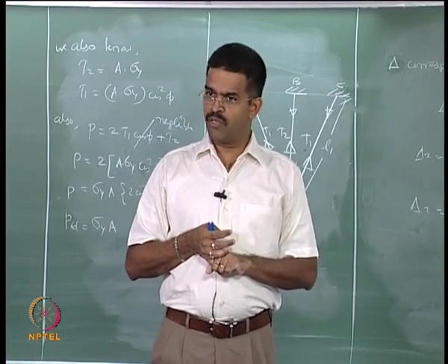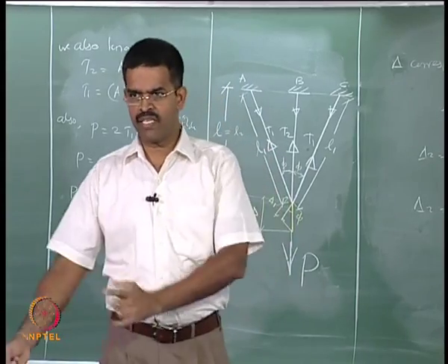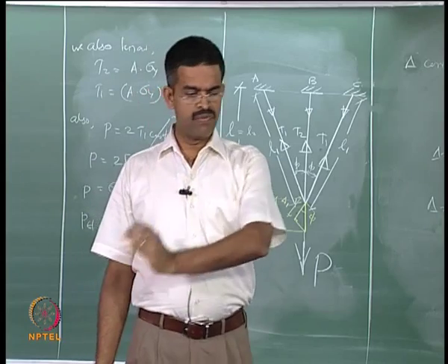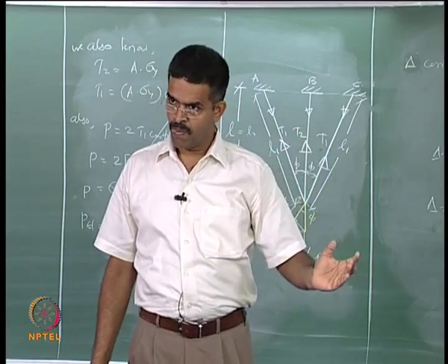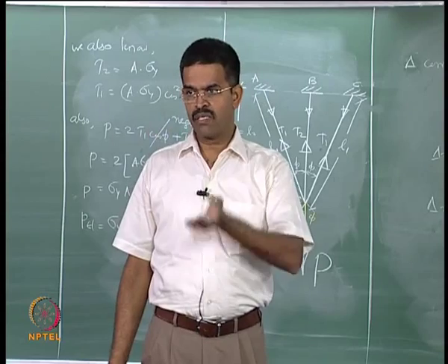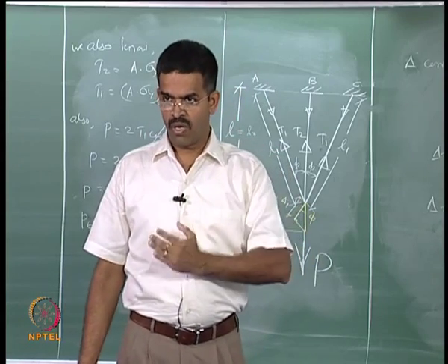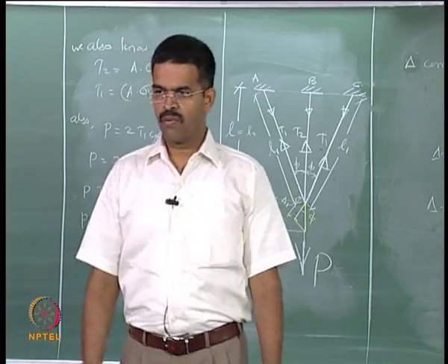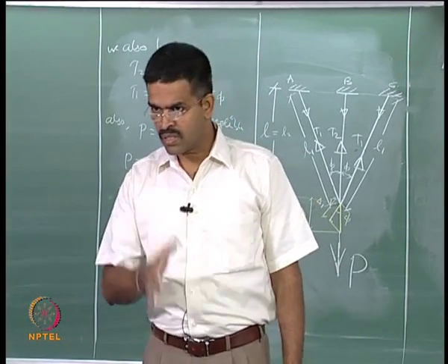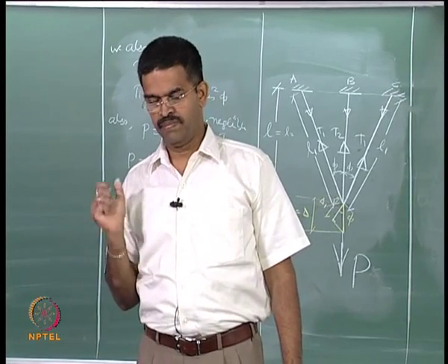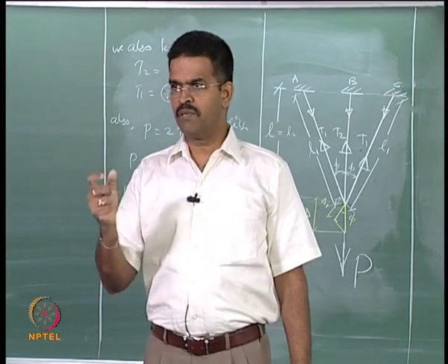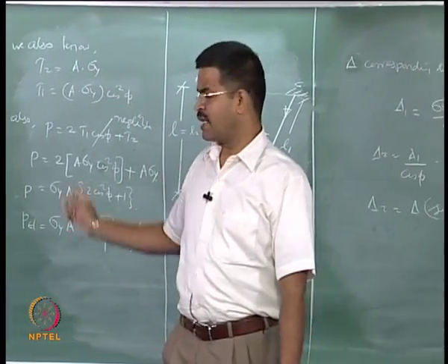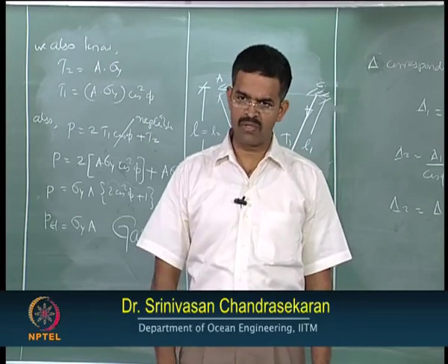So designers thought I can use that inelastic behavior as an advantage in my design. This is possible only when two things are available: one, enough ductility is present in the material; two, the structure should remain statically indeterminate, because this ductility is seen as a mechanism to redistribute the moments from a highly stressed cross section to the successive highly stressed cross section. If the structure is determinate, this redistribution is not possible. That is what we have seen. We have taken an example, explained how the gains and losses can be foreseen.